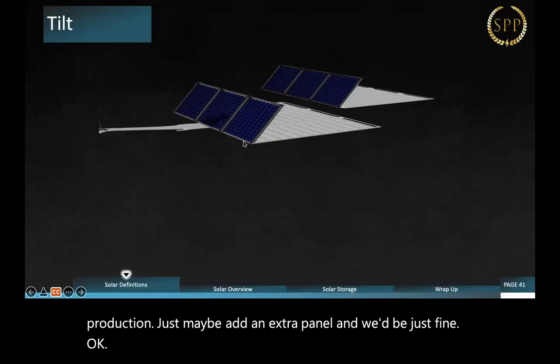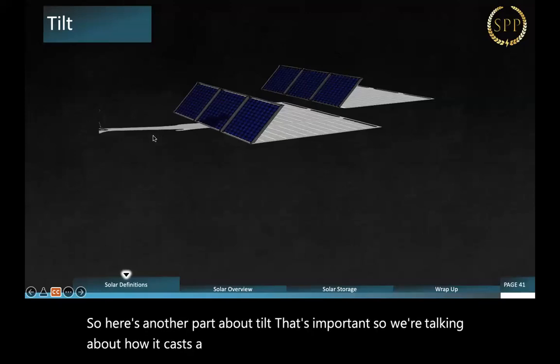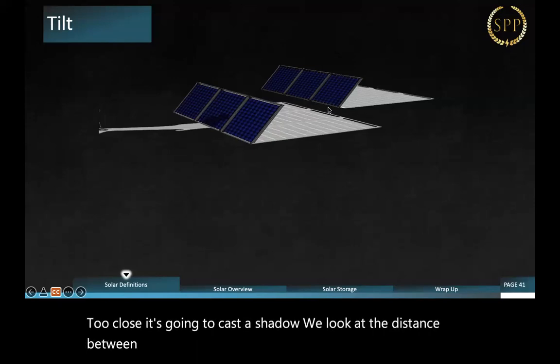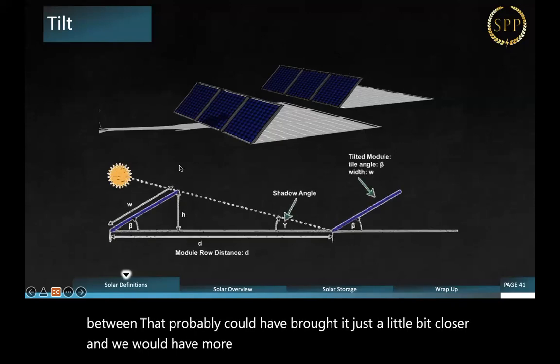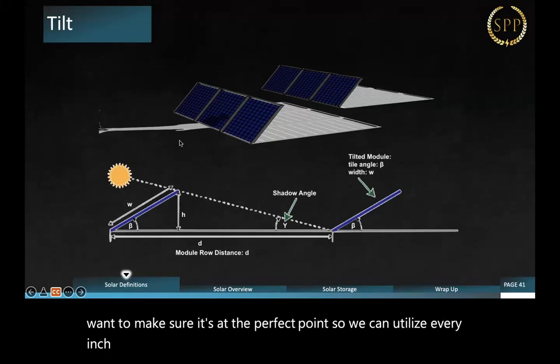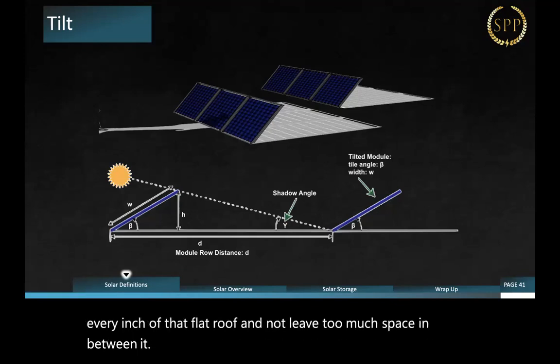So here's another part about tilt that's important. We're talking about how it casts a shadow. Too close, it's going to cast a shadow. Well, look at the distance between that. Probably could have brought it just a little bit closer and we would have more room. Because they do cast shadows, we want to make sure it's at the perfect point so we can utilize every inch of that flat roof and not leave too much space in between.